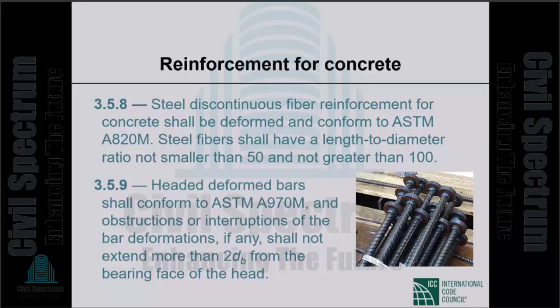And then headed deformed bars. Okay? So normally, to anchor a bar, we hook the bar into the concrete. But if it is a lot of reinforcement, the hooks lead to congestion, major congestion.